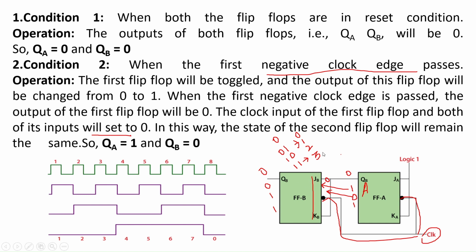Thus, we have discussed the basics of both the synchronous and asynchronous counter. We could design these counters for any number of states. Using two flip-flops, we have designed a counter that counts 4 states. We could count any number of states by adding the equivalent number of flip-flops.